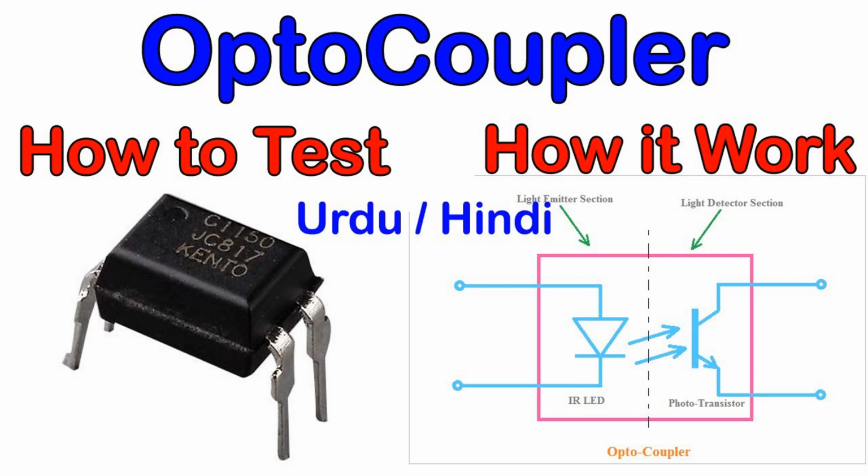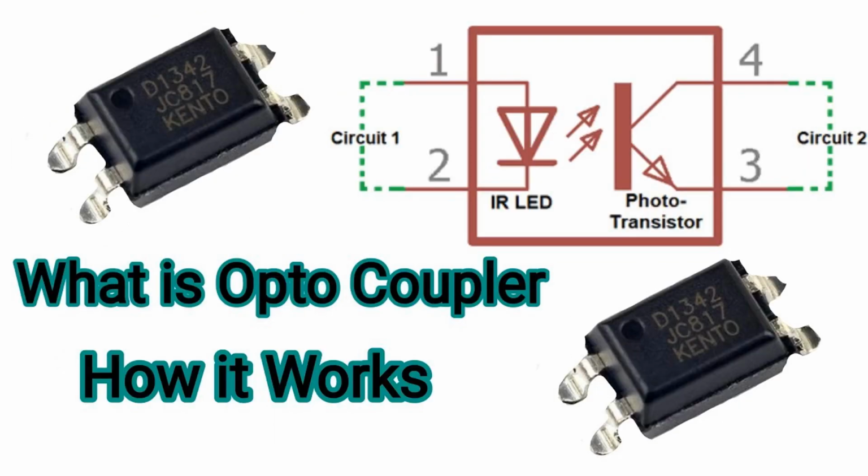Controller. The controller is a device or algorithm that calculates and generates control actions based on the error signal. It decides how to adjust the control input to minimize the error and bring the system closer to the setpoint. Controllers can be implemented using analog circuits, digital controllers, or software algorithms. Feedback path. The feedback path is the route through which information about the system's output is fed back to the controller. This typically involves sensors or measurement devices that provide data on the actual system output.